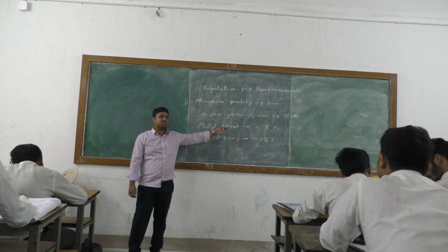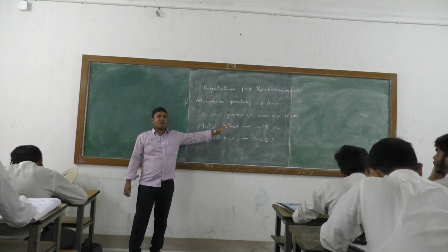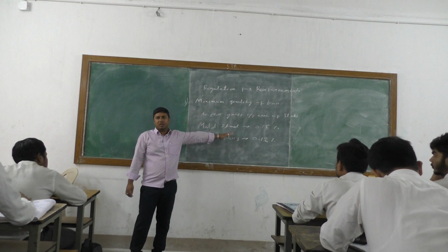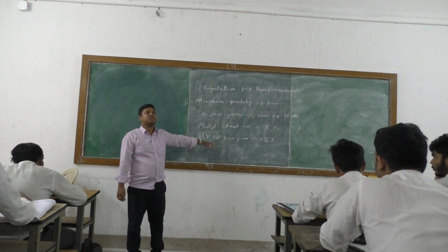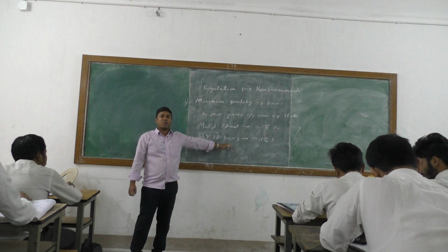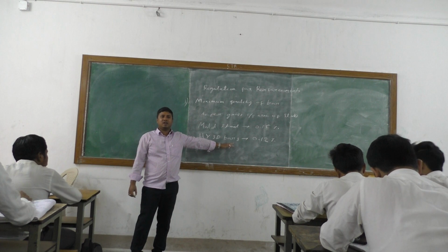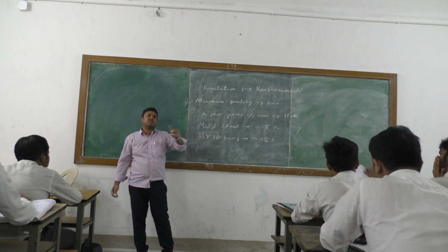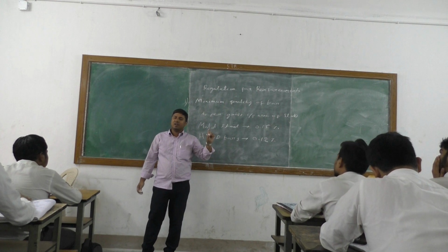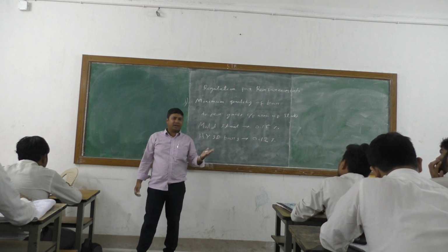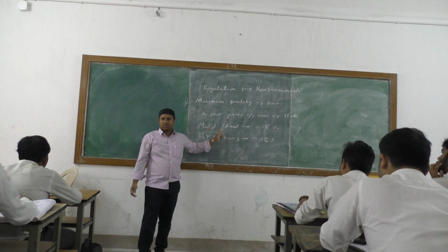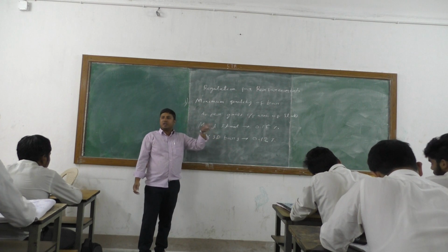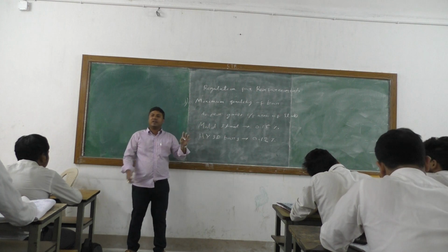Why is this difference there? I have already discussed in the shear class why the requirement for steel is more for your mild steel and lesser for your HYSD bar. For obvious reasons, the mild steel surface is smoother, and the yield stress is already lower. That is one point. Another point is that the surface is smooth for mild steel, whereas for the HYSD bar, is the surface smooth? It is ribbed.